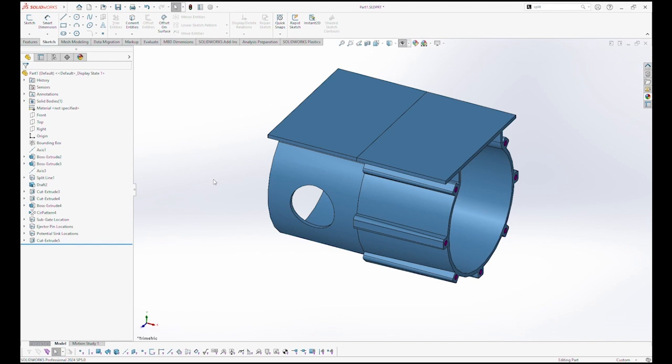And then the last category of finishing that I'll share with you are typically for optical parts. And you have a formula for these surfaces that you would like to have very clear, very transparent. And typically, what has to transpire there is that you have a nickel plated core that is then diamond turned with very precise equipment. And again, this finish is typically used when you're molding optical parts, and there's an upcharge for this service.